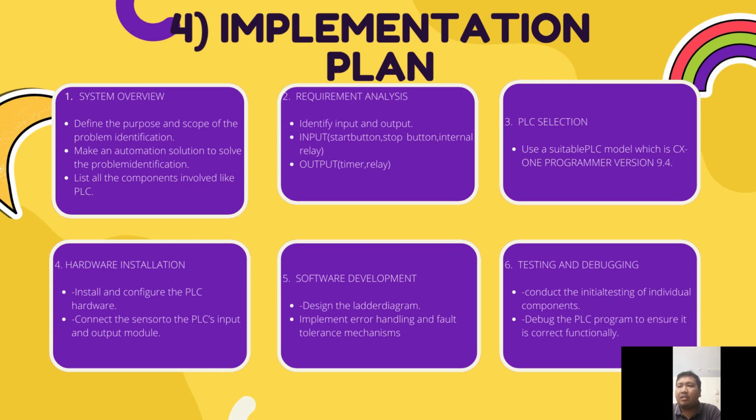Our third plan is PLC selection. We use a suitable PLC model, with CX Programmer, which is the software we use to make the ladder diagram. The fourth implementation plan is hardware installation, which is to install and configure the PLC hardware and connect the sensor to the PLC input and the output module. Number 5 is software development, which is to design the ladder diagram that we need to use and implement the error handling and fault tolerance mechanism.